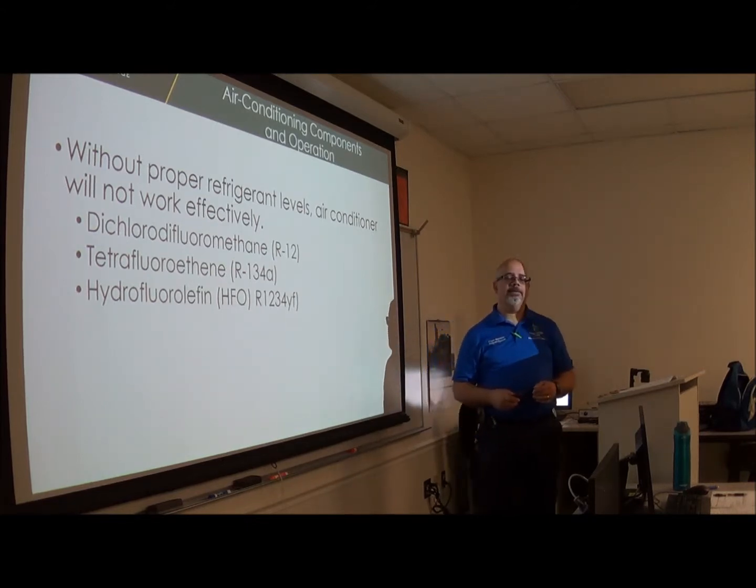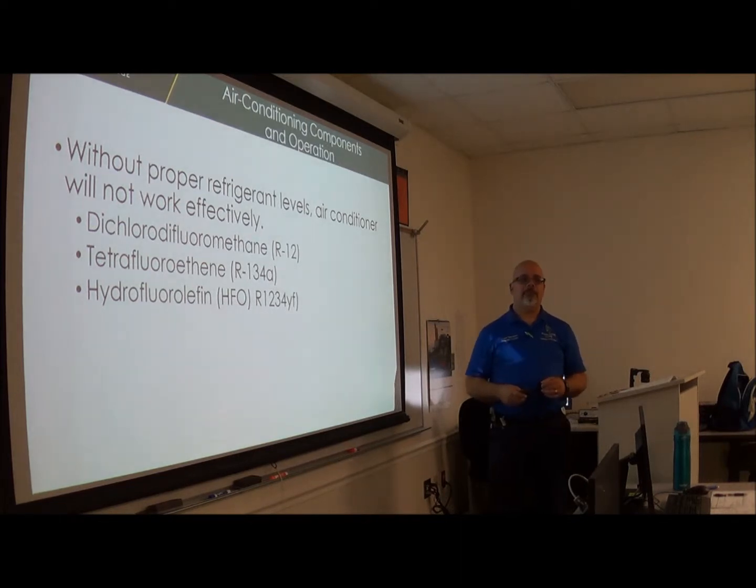Correct. It's the same when you hear a noise when it's starting something. That's when the compressor engages. When the compressor engages, it's taking power from the engine, so you hear that noise and you feel the RPMs go down a little bit, until they recover and go back up again, as soon as the computer understands that the compressor started.